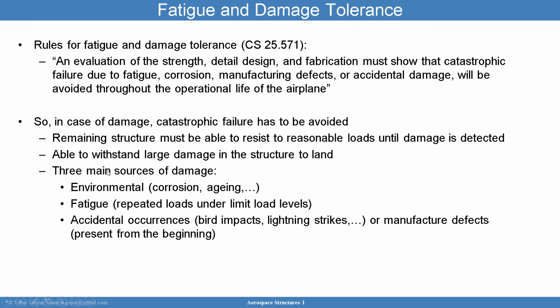The three main sources of damage, we covered a lot of these many times, but it's worth repeating, could be corrosion, aging, fatigue, and accidental issues like bird strike and lightning strike. Even when I have these kinds of damages, I should be able to land the structure successfully. And we have to make sure we can. Otherwise, catastrophic failure events could happen.